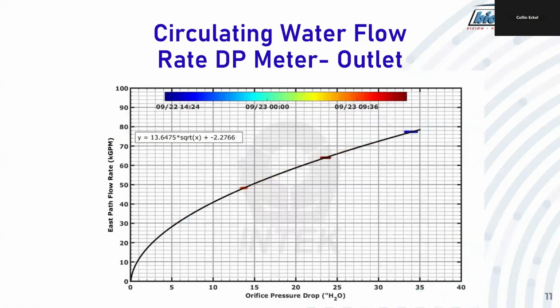The pressure difference between these 2 points at full flow is approximately 30 inches of water from the analysis. And you can see here at full flow, we were at 34, which is good agreement with the model. But it's also important to run the model at multiple flow rates, just so you know you have signal across all flow rates if you're running 1, 2, 3, 4 pumps.